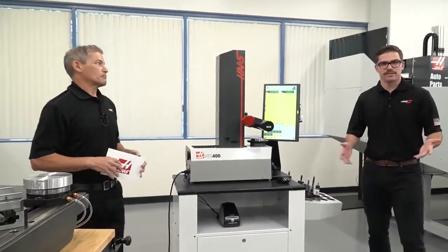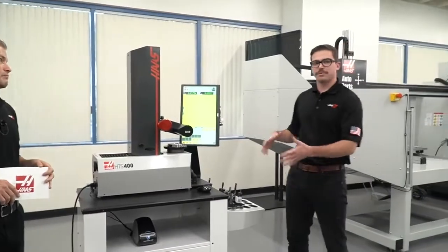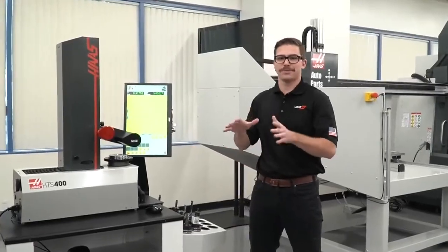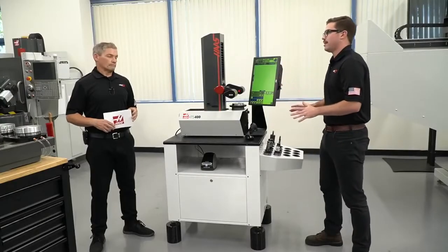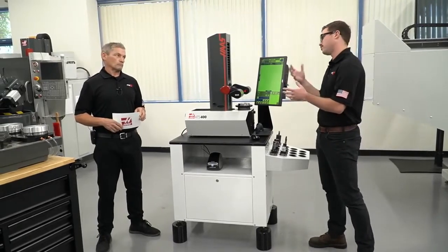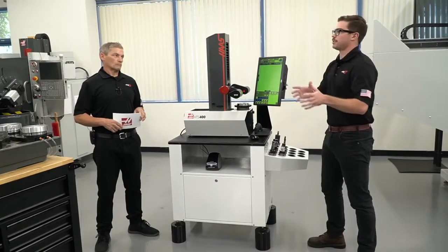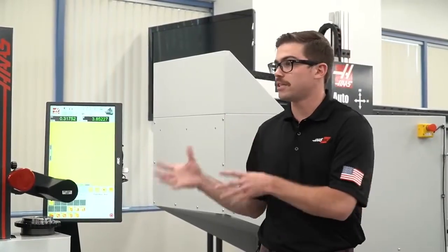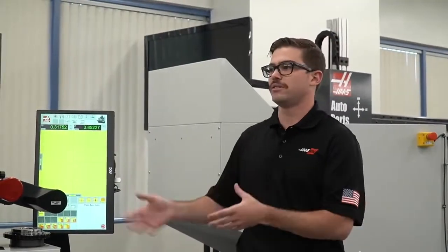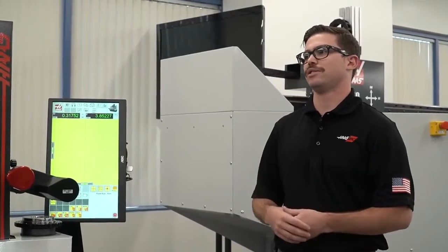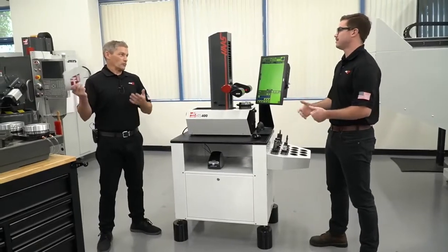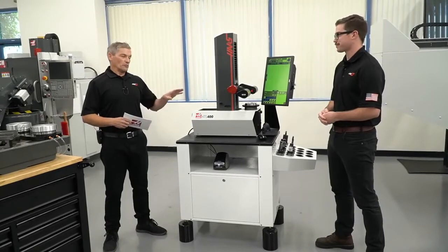Yeah, so for those of you who haven't encountered a tool presetter before, essentially what a presetter does is it takes the operation of touching off and setting your tool offsets, which has to be done primarily inside of your machine, and makes it something that can actually be done offline. So it allows you to continue to be making parts and continue to run your spindle, while still being able to touch off your tools and set up tools, either for replacing the tools in your current job or setting up a brand new job. That just allows you to make more money at the end of the day. You're running your spindle longer and more often per day, so you're making more money. Exactly. Cool. So something that's going to pay off for sure.